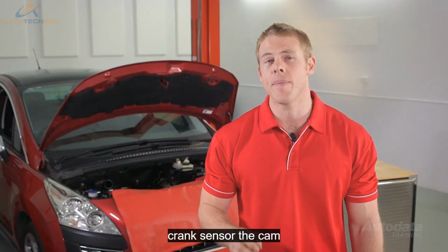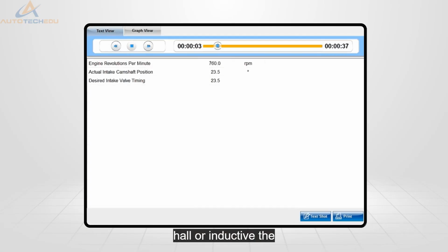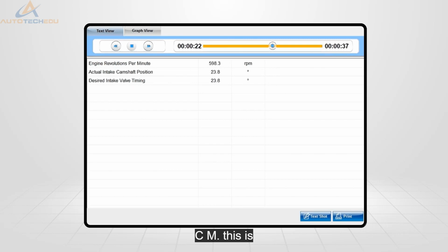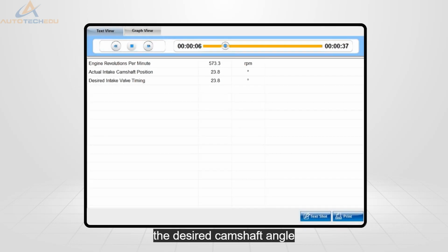Like the crank sensor, the cam position sensor can be either Hall or inductive. The cam position sensor provides cylinder event information to the ECM. This is what a good cam position signal looks like at idle. It should reflect the desired camshaft angle.